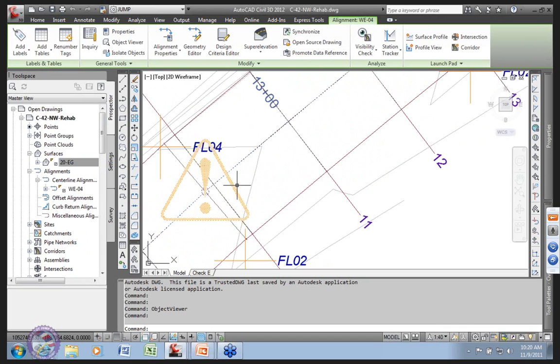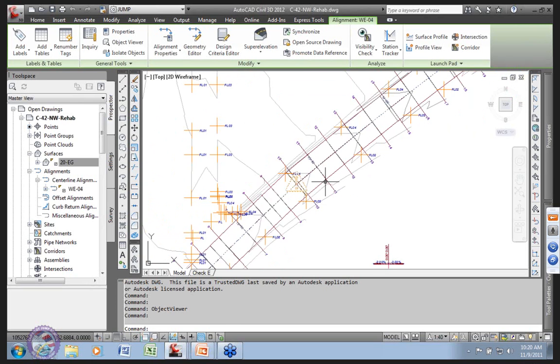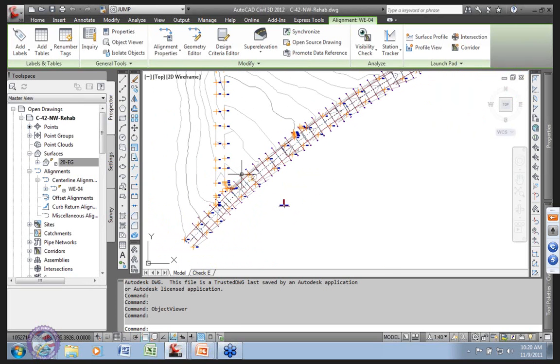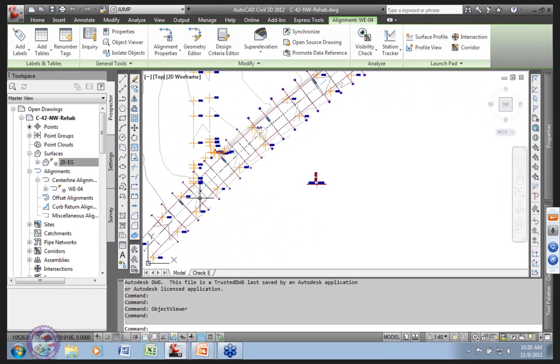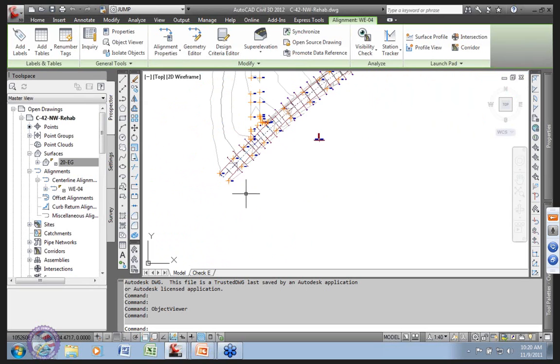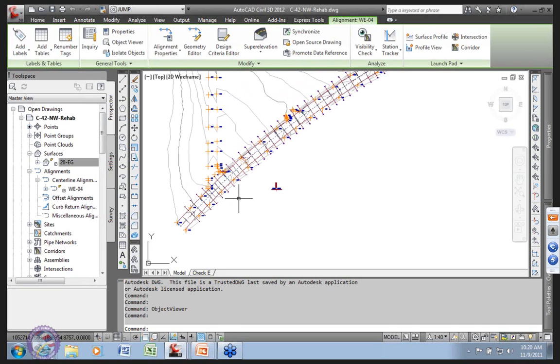But anyway, so I have a reference alignment, okay, based on record stuff. Civil 3D is squealing and telling me, hey, according to record, these are two non-tangent curves, so Civil 3D immediately gives you some feedback about that. And because I need that alignment, and I'm going to need to have a corridor, because a corridor is going to do most of the work here. All corridors require an alignment profile pair, even if I'm not employing one of those parts, right, in my project.